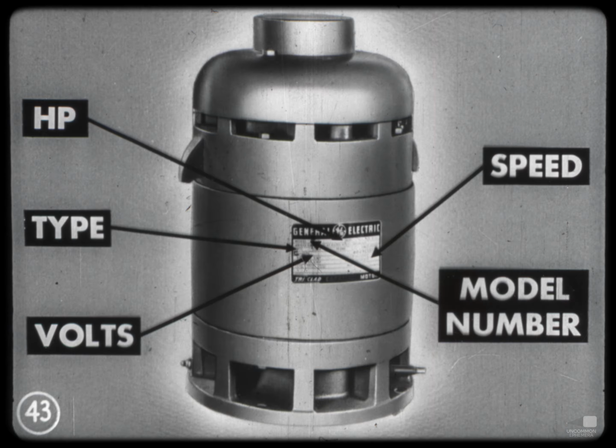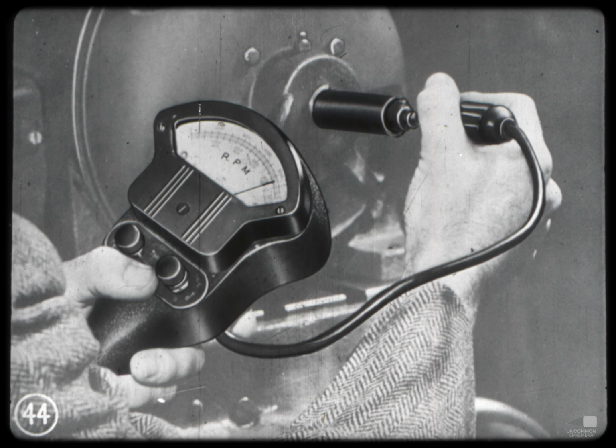In replacing a motor, data from the old motor nameplate can be used, provided any changes that have been made are taken into consideration and that operating characteristics of a new motor of that type will do the same job. If there's any doubt, however, it's wise to recheck the application and run a load test if this can be done. One check is to measure the motor speed under normal load with a tachometer or speed indicator.